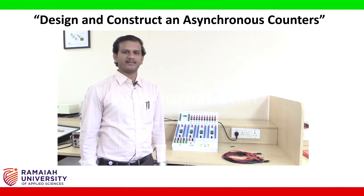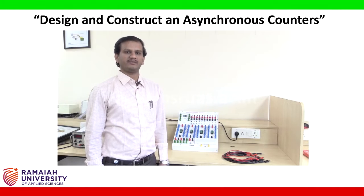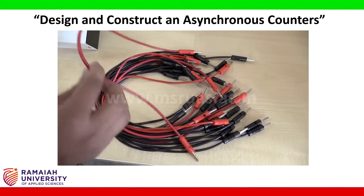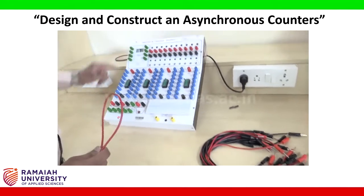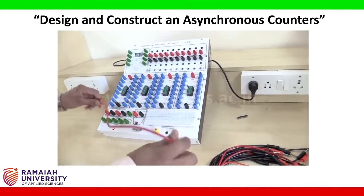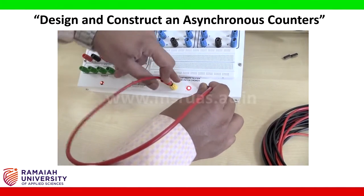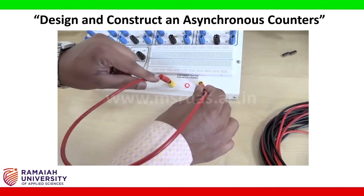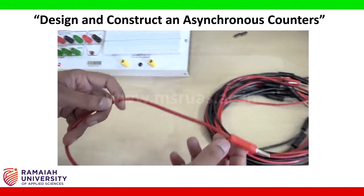Before connecting the logic diagram, let us check the continuity of the patch cords by placing each patch cord into the continuity tester. So take the patch cord. Turn on the power supply of the digital IC trainer kit. The LED bulb is on, the power supply is on now. So now we have to place each patch cord into the continuity tester. There is a beep noise and LED is on, that means this patch cord is working. This test is performed for all the remaining patch cords in a similar way.